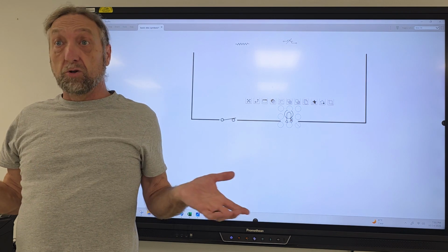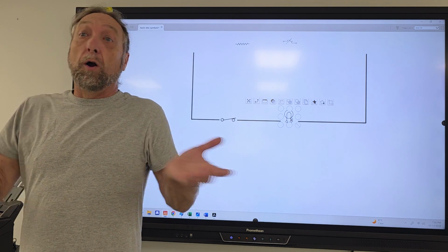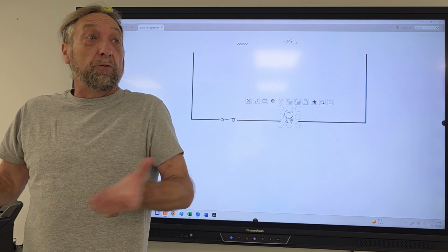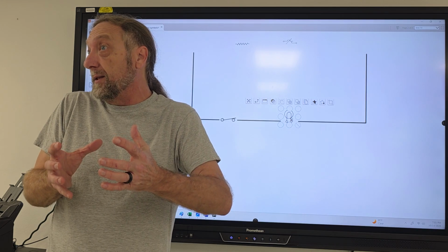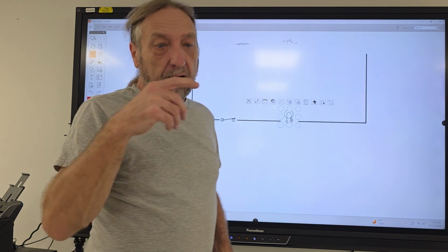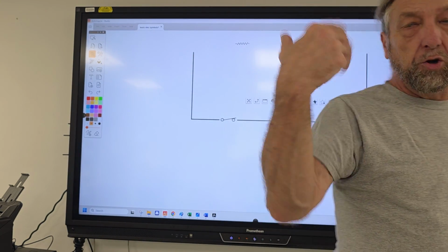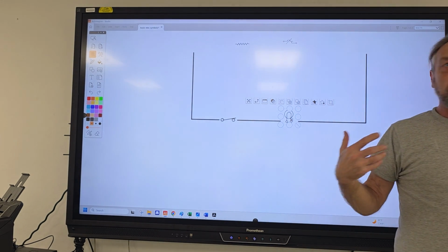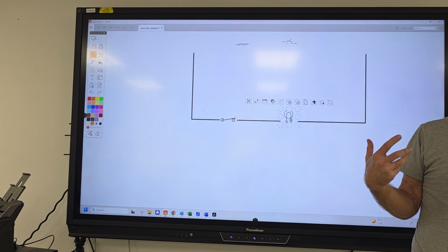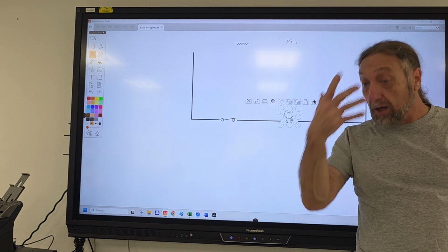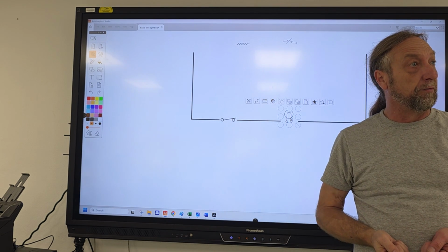Yeah, the drain pump. Or it could be the main motor on the direct drive Whirlpool washer, the main motor, the pump's attached to it. Okay, but what I'm saying is your troubleshooting of an appliance begins the moment you talk to a customer. It doesn't begin the moment you start looking at the diagram and start taking parts off.